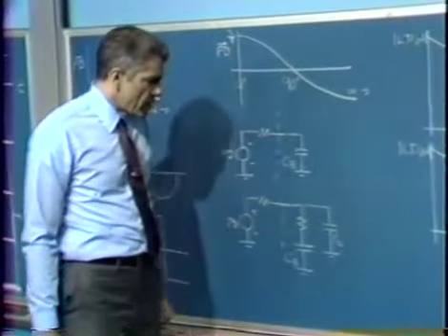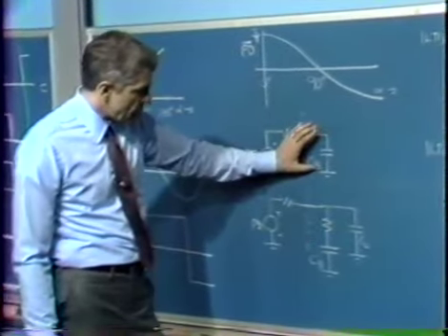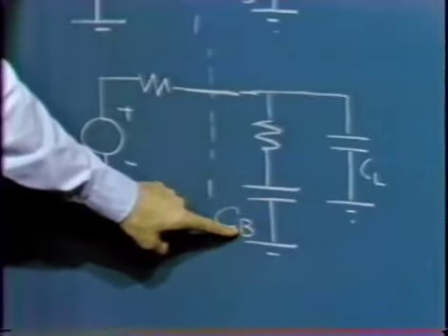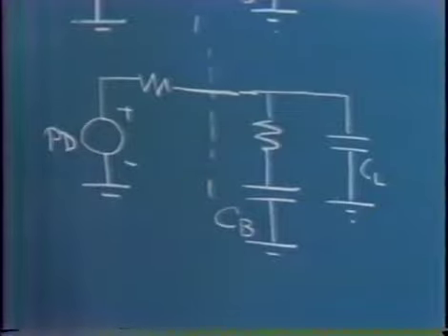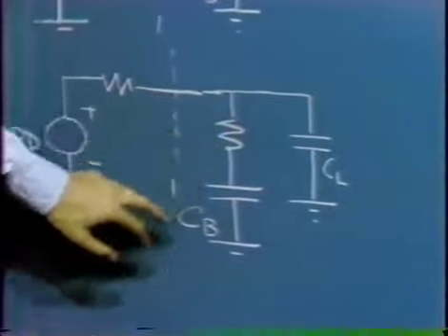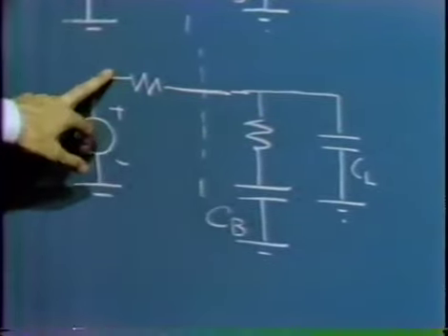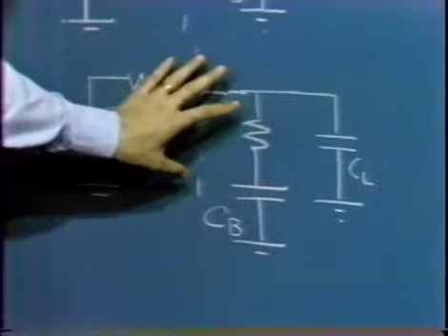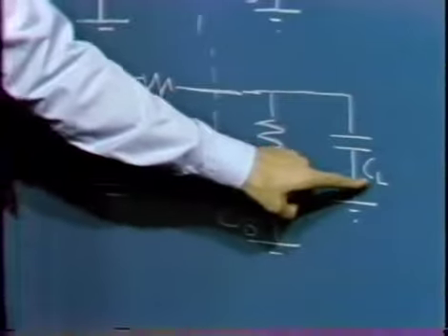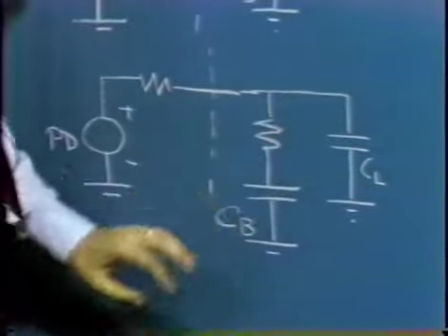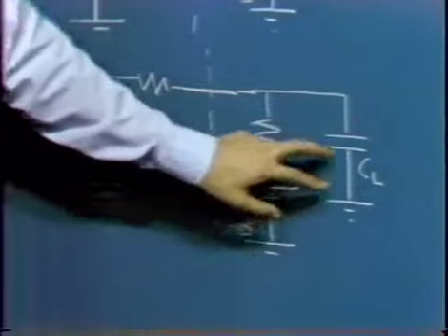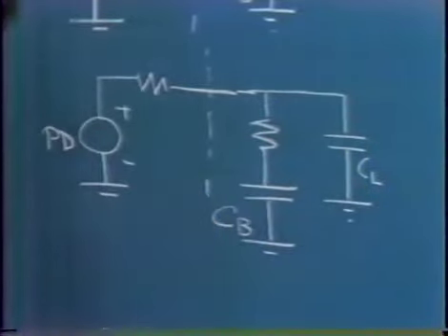We can use a slightly more complicated network at the outside of the package that looks something like this. We have our C sub big, which might be the same value as before, but then we can put a series resistance associated with that. At high frequencies, we get simply an attenuation between this point and this point. Then we get lag kinds of transfer functions out of that combination. We might then put a smaller capacitor across this network that would provide additional ripple filtering at high frequencies. So the purpose of this is simply to provide ripple filtering.